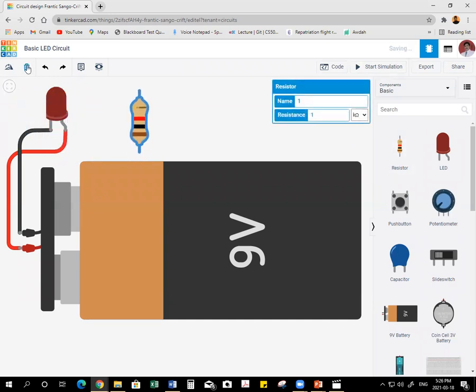Okay, I can rotate this resistor. Now another beauty of the resistor is that you can give it a name, R1, no problem. Here you can put whatever value you want. This is in ohms, kilo ohms, mega ohms, giga ohms, and also milli ohms, micro, nano, pico ohms. So predefined values are available.